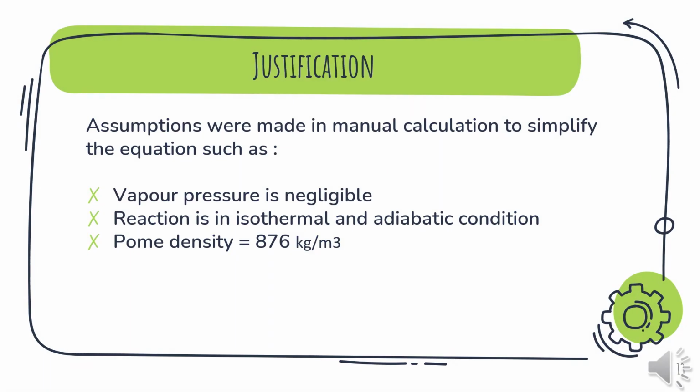It can clearly be seen that there are deviation errors in all the values when comparing HYSYS simulation and manual calculation. Besides, the manual calculation is made according to the model equation and many assumptions have been made to simplify the equation, which has caused deviation error. All in all, manual calculation is mainly for reference in modeling reactors. However, real-life processes must be taken into consideration, as assumptions made to simplify the model equation are hard to be done realistically.